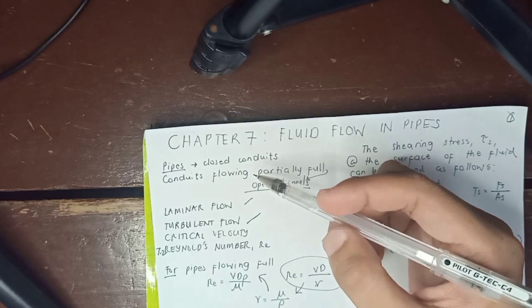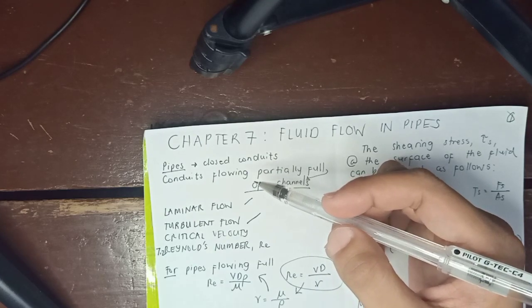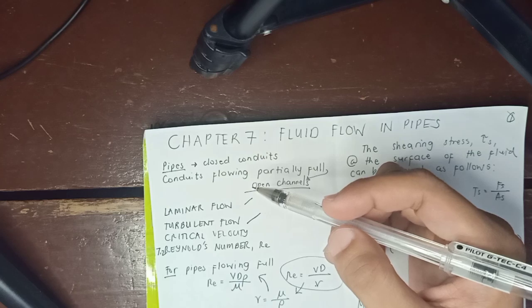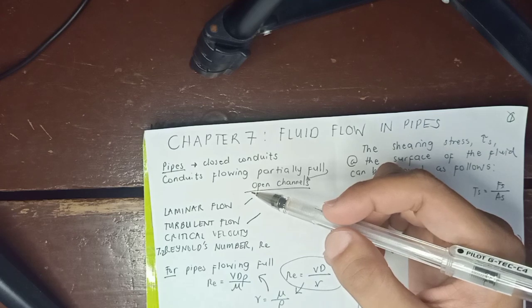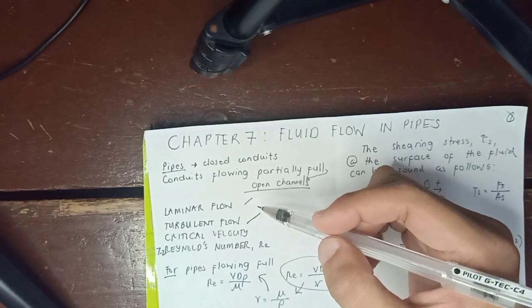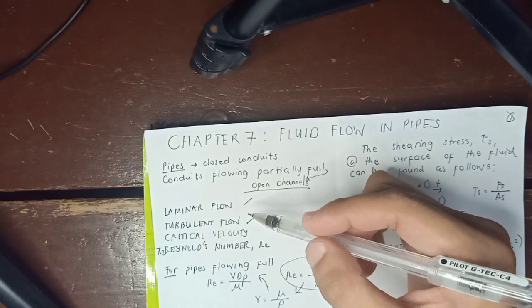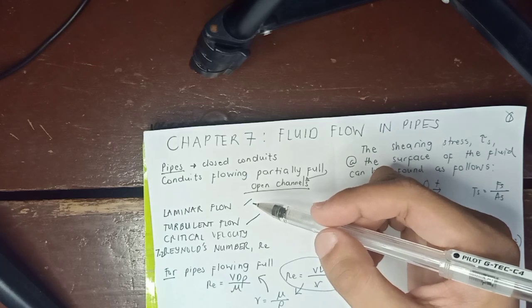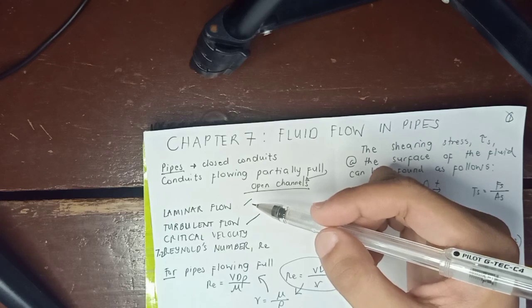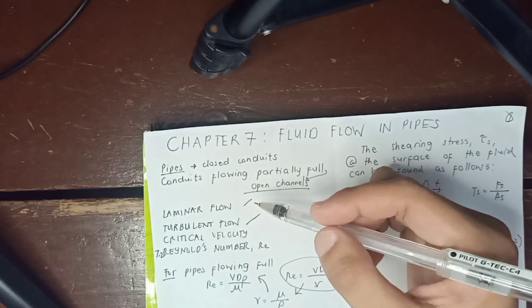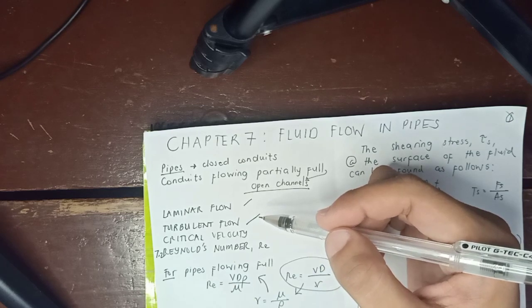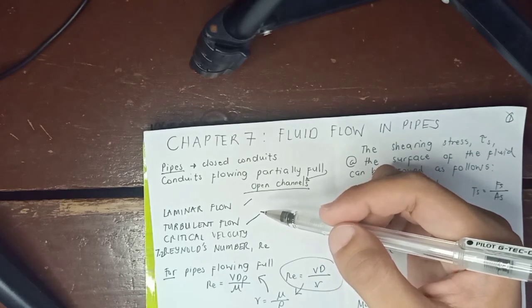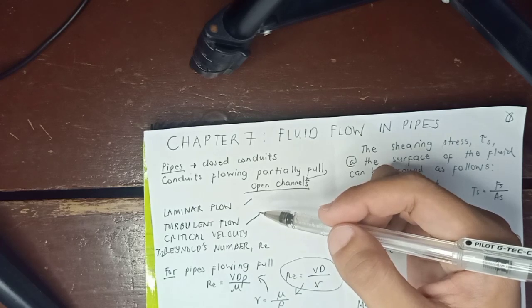Laminar flow is said to be laminar when the paths of individual fluid particles do not cross or intersect. The flow is always laminar when the Reynolds number is less than 2000, while turbulent flow is said to be turbulent when the paths of individual particles are irregular and continuously cross each other. Turbulent flow normally occurs when the Reynolds number exceeds 2000. These two were just mentioned in the earlier chapter, and I hope you have retained the information I have said to you.